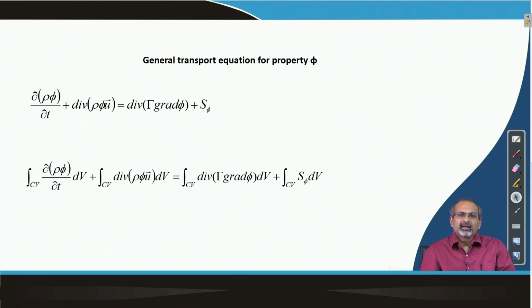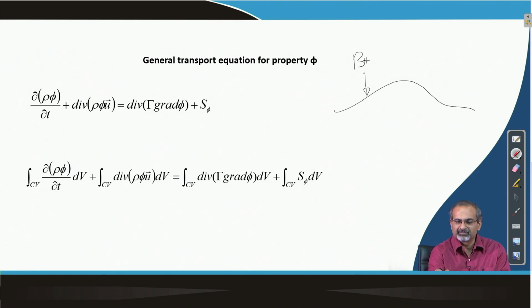Again, remember that in finite difference calculations, using non-uniform mesh is always more complicated, while that is rather easy to do in finite volume technique. Again, if you have very complex geometries to work with, finite volume is a much more flexible and easy to adapt method compared to finite difference method. For example, if you have very strange looking surfaces on which you have to implement certain boundary conditions in a finite difference framework,